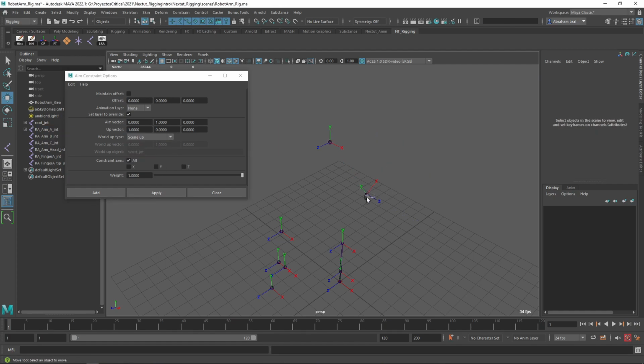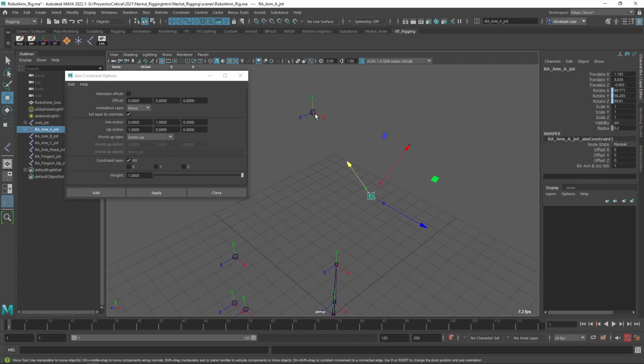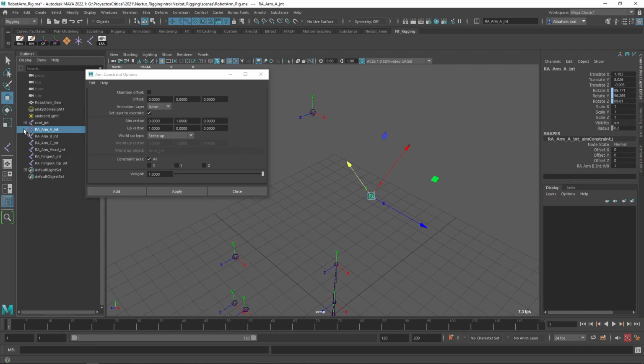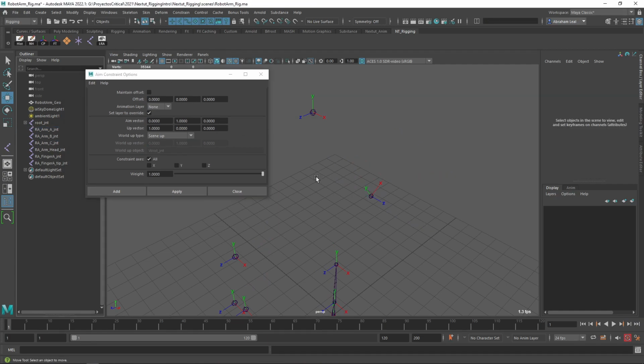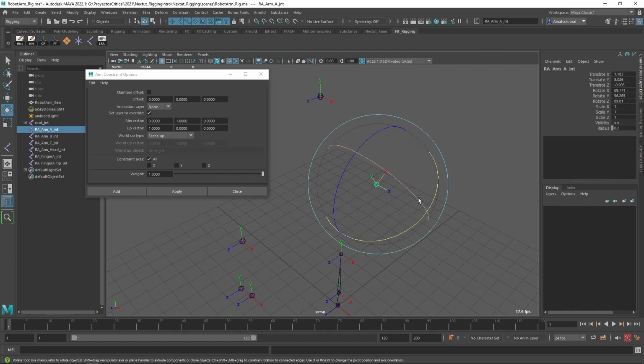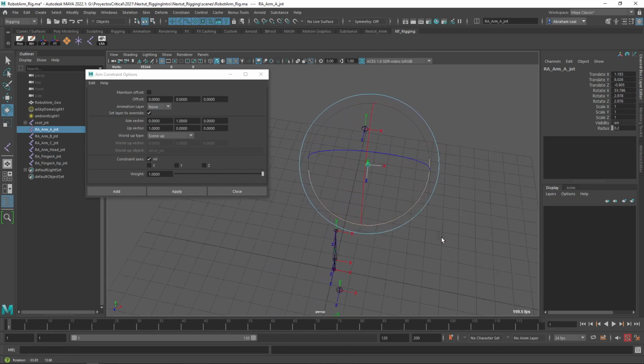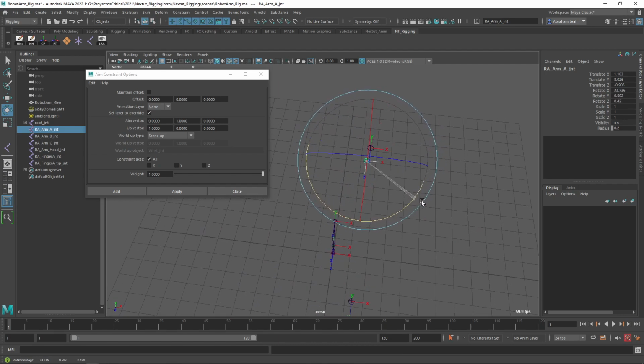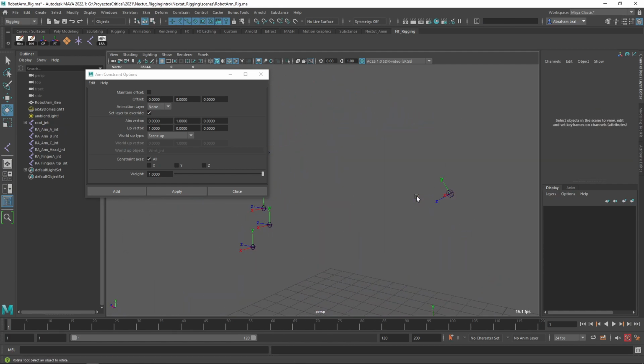Okay, I'm going to show you something cool here. So now I'm pointing towards the y-axis in the proper way. The constraint I no longer need. I just used it to get this first position. And now what I'm going to do is rotate this thing with snap rotate here. I'm going to press E, click, and select discrete rotate. And I'm going to rotate this until the x-axis is pointing towards the x-axis, like this. So now the y-axis is properly pointing towards the front, and the x-axis is properly pointing towards the side.